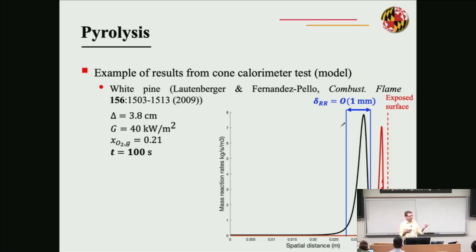I think Dr. Simeoni said this morning that there is nothing really new about the physics that we are studying. It is true we understand somewhat the pyrolysis. The pyrolysis is still difficult, but we certainly understand the fluid mechanics, the combustion, the radiation heat transfer. We have made great progress on these disciplines. But the coupling between all these phenomena is the difficulty. We still do not understand the spread of a fire because we don't really understand how these different pieces of the physics are coupled together.